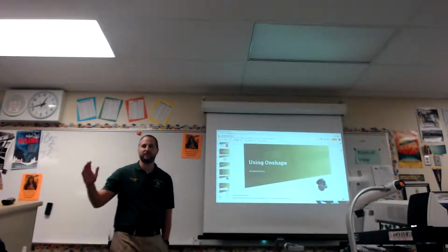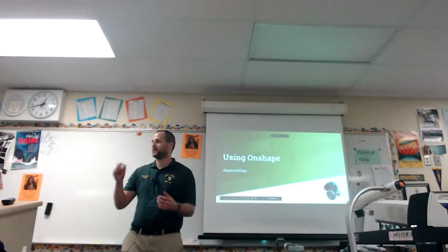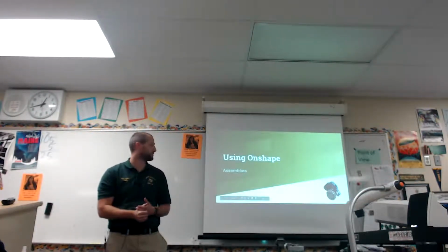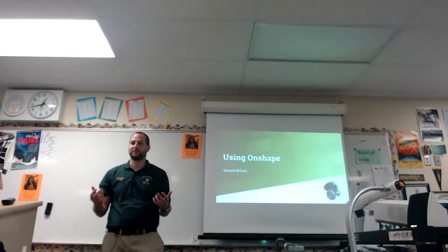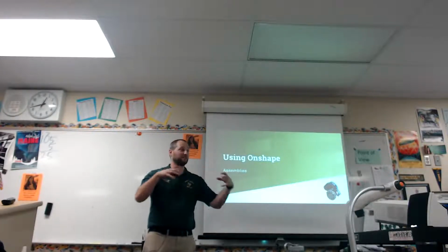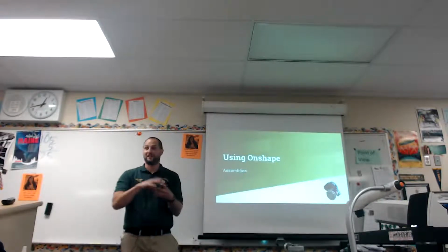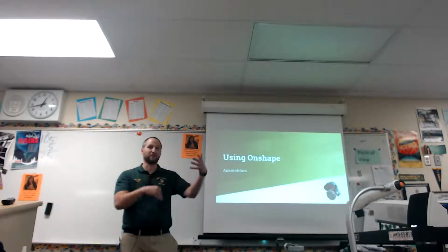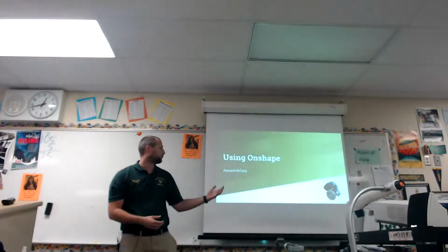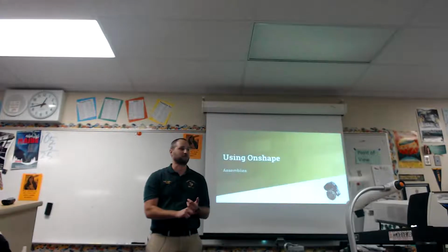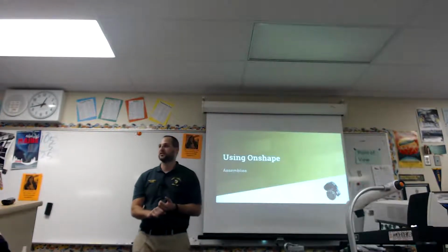So parts and part studios, right? A lot of that's the same. You do have those benefits of building the parts out uniquely within the context. Assemblies become a little bit simpler because if you build your parts together in your part studio and everything fits, then when you go and do your assembly, everything's going to fit because it's already built to fit together. One of the benefits of doing it this way is in your parts and part studios, you build all your static structures, and your assemblies are only there to show motion.